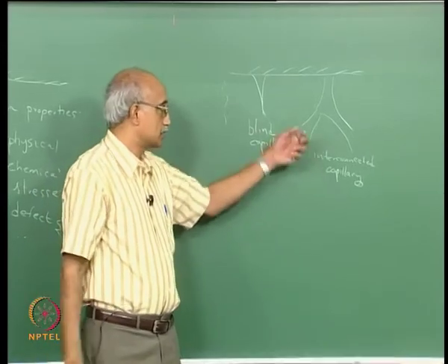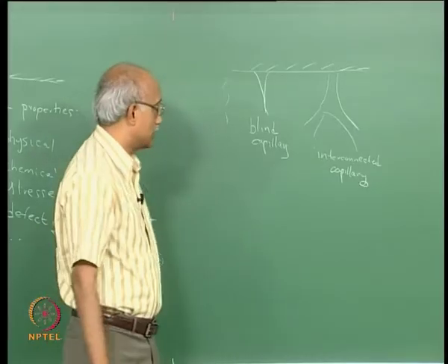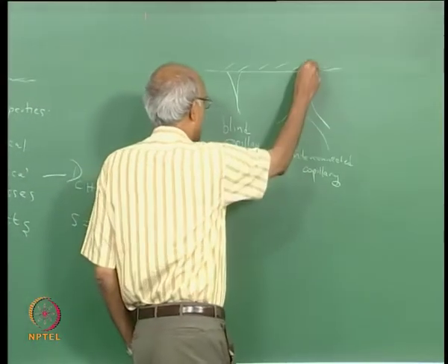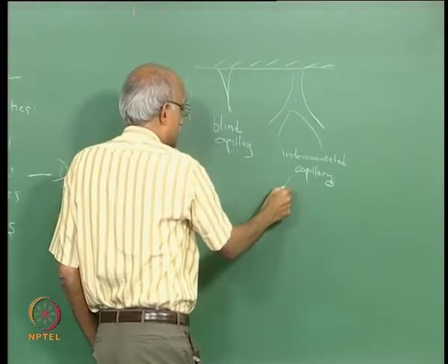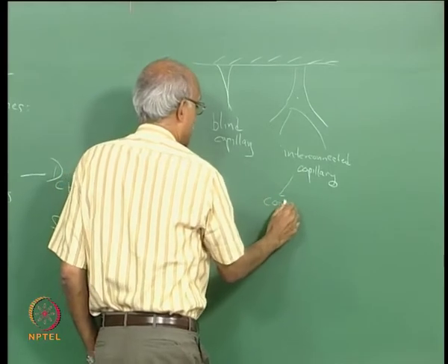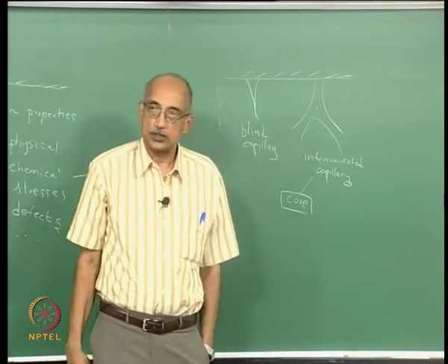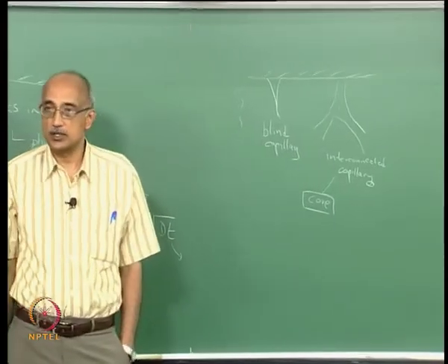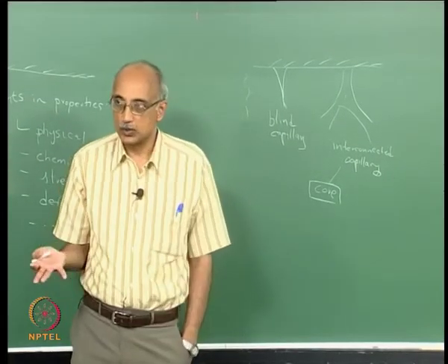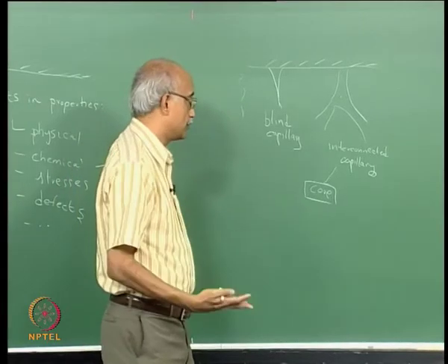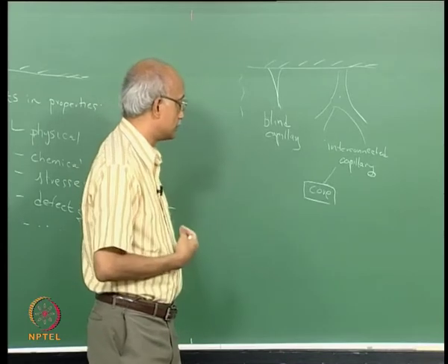Now when this happens, the propagation of the liquid through the particle will be much more extensive, and it can get transported not only at its local area of entry but throughout the surface, and there is a possibility that this can actually extend all the way to the core of the particle. So depending on what you are trying to achieve, you can either try and minimize these capillaries or try and maximize the capillaries, depending on how extensive an interaction you are looking for between the surrounding fluid and the particle that is suspended in this fluid.